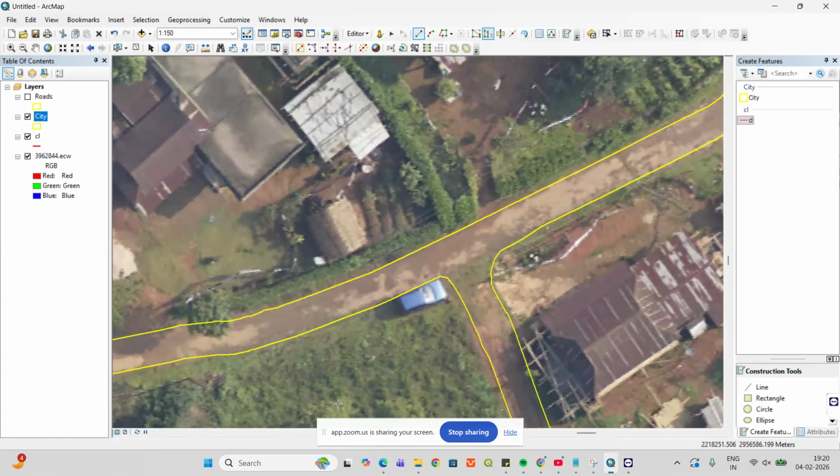So you'll be providing them the GCP marked area, I mean the lat and long details. We'll be preparing a KML or giving them the zone. Like, this company will get this zone. We'll split it into multiple zones, just like administrative boundaries. We'll split it into multiple zones A, B, C, D, E, and we'll mark GCP also zone wise only, so that we will not get into confusion.